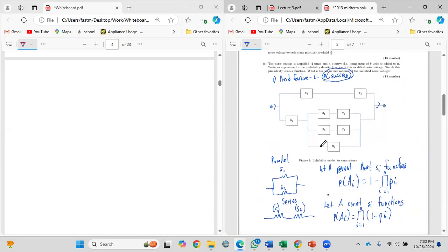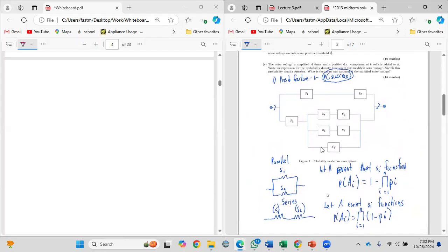So let's leave that there and run through the question. The first thing we do is treat this like a normal circuit, and you're just trying to get the Boolean expression like normal. If I start here, I have two ways I could go. I could go through S1 and S2 to get out, or I could go through S3 and the parallel combination of all these to get to the outside. So it's in parallel, and you have some series elements inside of it. So the first piece works like normal Boolean algebra.